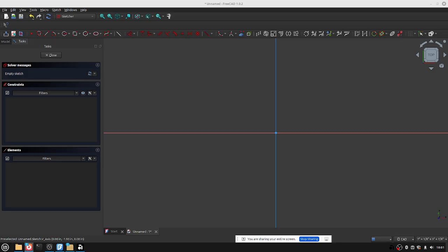All right, so there's a couple of different workflows you can do in FreeCAD, and it does have a very powerful sketcher. The idea is that you can take two-dimensional sketches and then turn that into 3D pretty easily. The typical workflow that we use is to sketch things out, any kind of geometry, in the sketcher, the two-dimensional part, and then take it out into 3D.